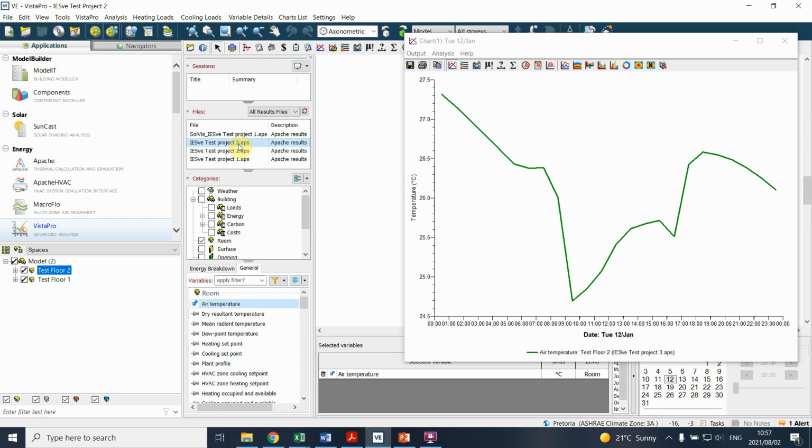If we start opening windows, we see a little bit of a different flow. In the morning, the temperature is quite warm. It drops down. It's summer, so it's above 25 degrees. But at 8 or 9 o'clock, someone starts opening windows, and we see a dramatic drop in temperature. And then slowly we see the temperature gaining again. So clearly the windows are working, but not necessarily that well, because by 5 o'clock it's still 25.5, and then the windows are closed and we see a temperature gain.